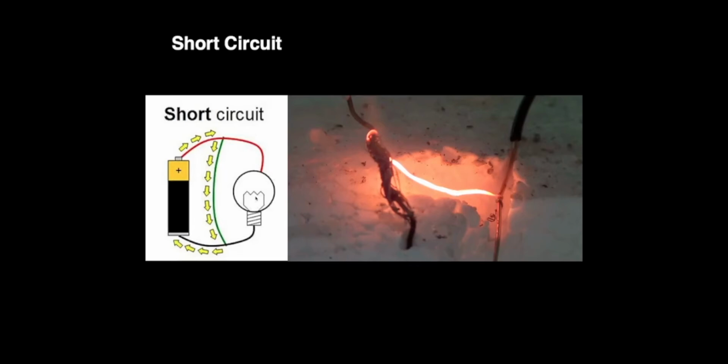something else on fire. So you just have to be careful with short circuits where you're basically doing just a loop that doesn't have a load attached to it like this. So if this green wire wasn't there, then it would be fine. The LED would be taking that current and turning on and using it, versus this wire has nothing to output that energy. So it just gets really hot and then could catch on fire.